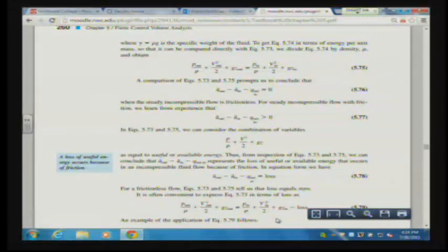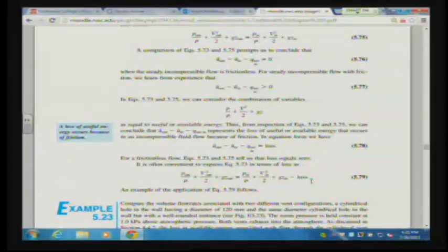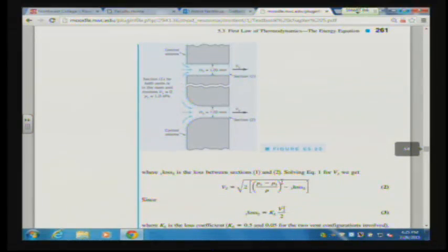And you can do the same for gains. When you have a pump, for example, you may notice that a pump is rated as so many horsepower. That is actually a power, or a W dot, that you can put into the system. So if you know something about the quality of the pipe, the quality of the friction between the fluid and the pipe, and you know something about the rating of a pump, you can use the Bernoulli equation to express those ideas in terms of a relatively simple equation. And the rest of these, we have some examples of what those are going to look like.